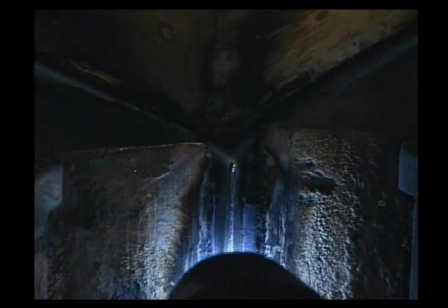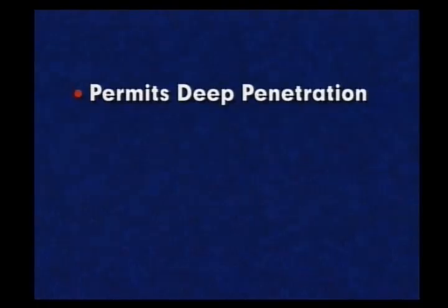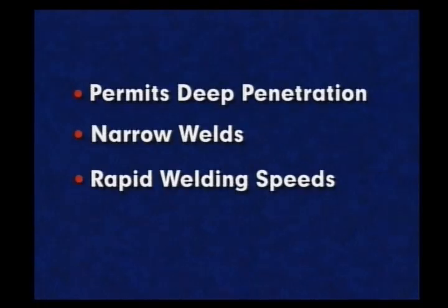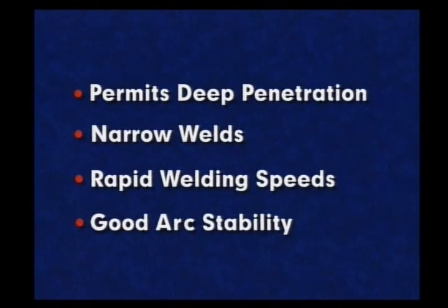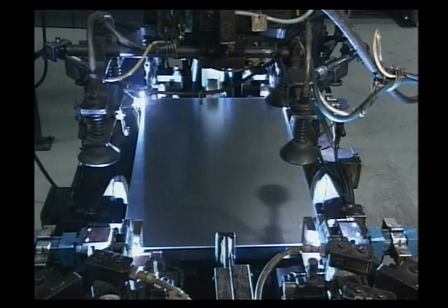Because of the constricted arc, the heat energy of the plasma stream is concentrated and extremely intense. This permits deep penetration, narrow welds, and rapid welding speeds with good arc stability. Workpieces can be joined with or without filler metal.